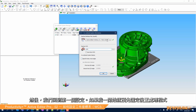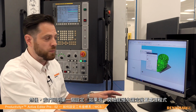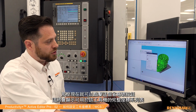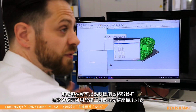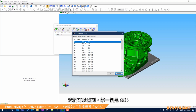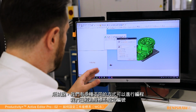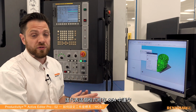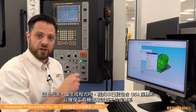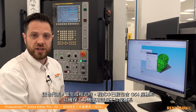And actually, if we come back to that first setting, if I select my post processor up front to begin with, that also means we can use this ellipsis button, and that will give you the list of coordinate systems that are available for this particular machine tool. As we can see here, number 1, G54. There's lots of different ways you can program that. So we've given it its designation. Now this means this program is going to work in G54, and when I generate the program, G54 is going to be output to make sure the machine is in that work offset.